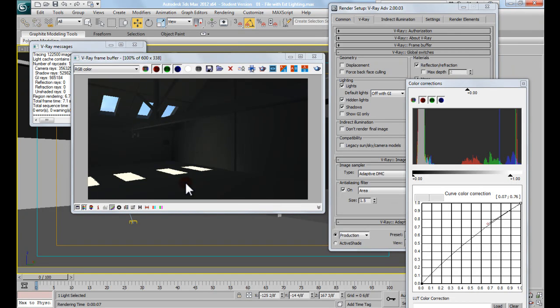It's actually taking the geometry. The displacement is taking that geometry, which is just flat, and popping out the bricks. Literally, it's like if you were to go in there and cut it up where you have your joints, and then take the faces that are in brick and extrude them out. That's what that's doing for you with an image. We'll go over that in two classes.